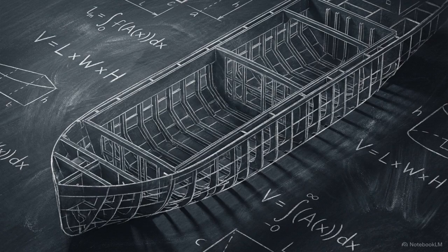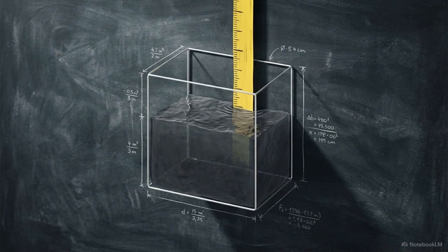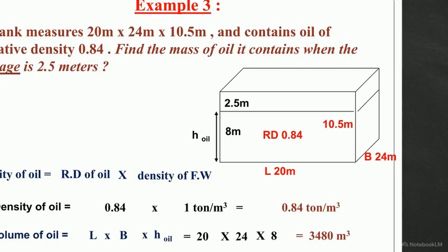Knowing the density of the fluid is only the first step. The equation must also account for the physical constraints of the steel tanks holding that liquid. A theoretical calculation of a tank's maximum volume doesn't work in practice. Engineers must factor in physical clearance requirements, a concept known as ullage. Ullage is the precise measurement of the empty space deliberately left between the surface of the liquid and the ceiling of the tank.